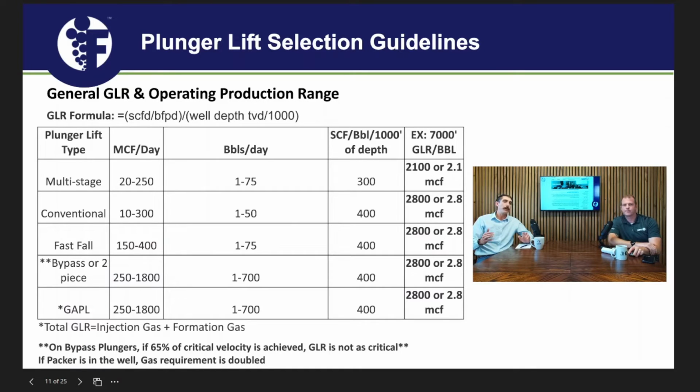Right. And it's very common too, if you have a packer, go in and punch a hole below wherever your bumper spring's going to be. Now you've got that communication. Now that gas can access the annulus, and you've got that storage. Okay, and that's cheaper than having to get a workover rig to pull just a packer to put the well on plunger.